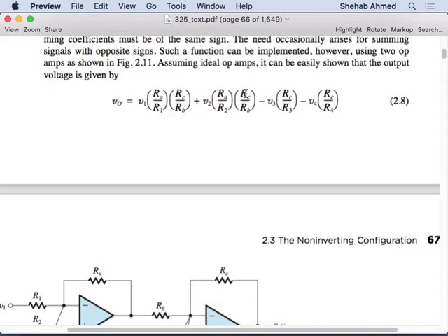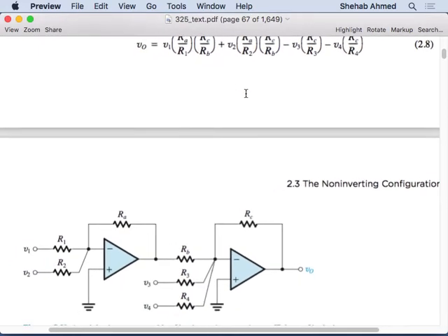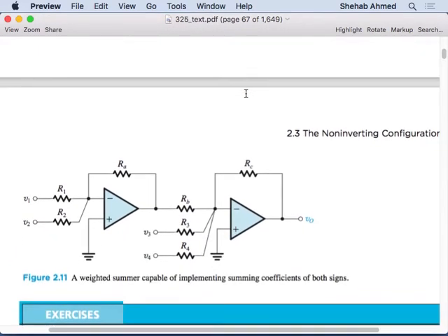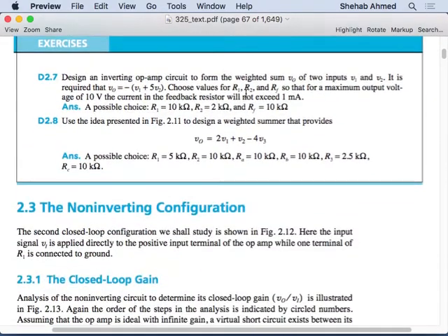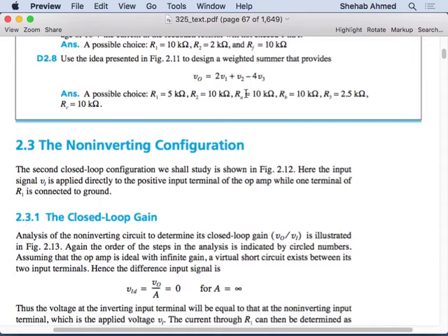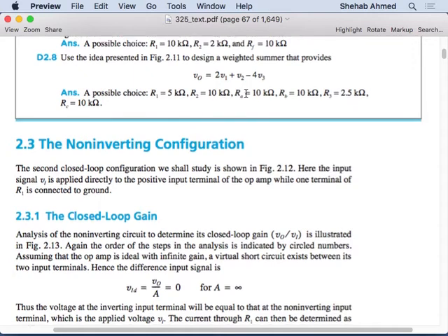So this is another application of that. You have the negative because of the stages, two inverting ones. Okay, any questions on this? This is called a weighted summer. You can think of it as a weighted summer, weighted subtractor, just like this summer, exactly. You're weighted with gains, of course.